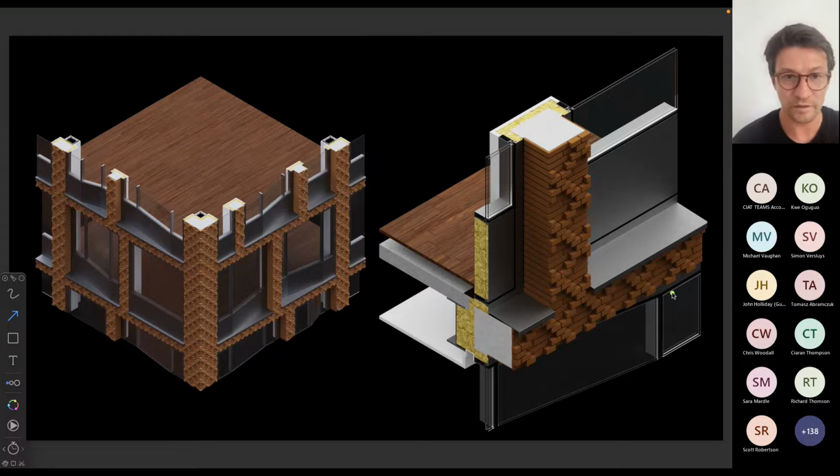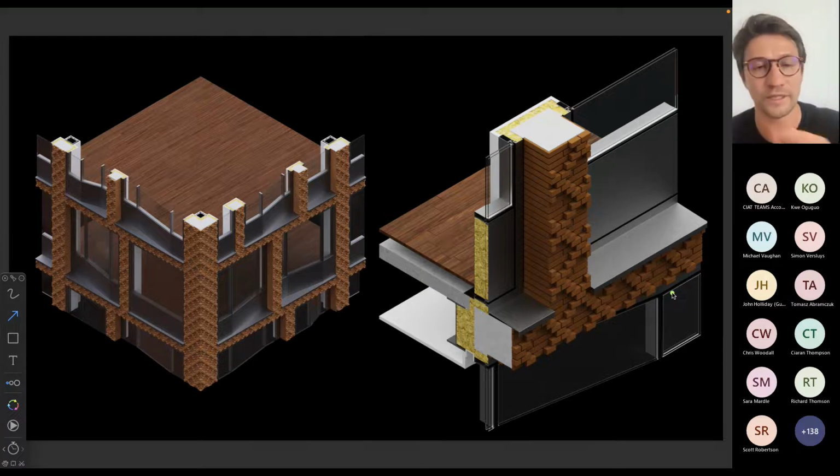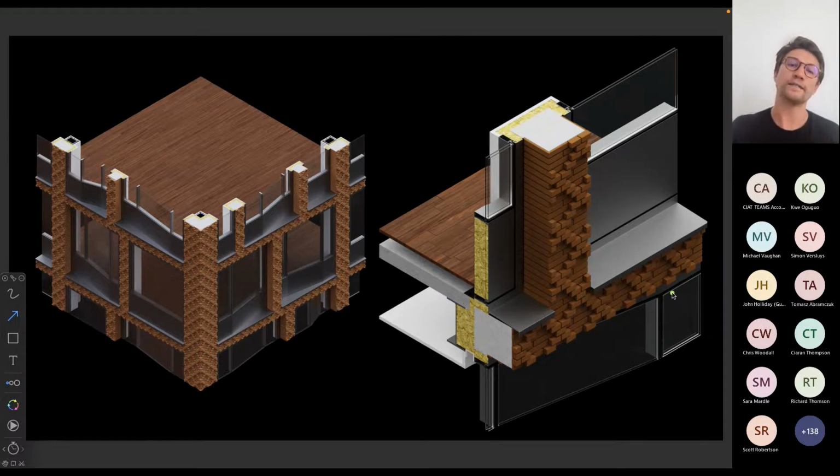For that element, as I said at the very beginning, this could sometimes also be achieved with simple GFRC elements, not necessarily entirely precast concrete, but in this particular case study, it is precast concrete beams and columns, and the windows would be installed retrospectively, once the whole frame is installed. In this case, precast brick is worth considering where you have really complex, onerous patterns that need to be achieved off-site.